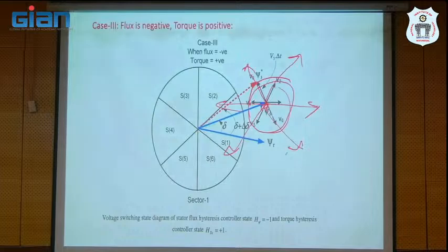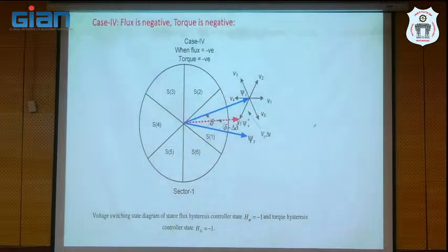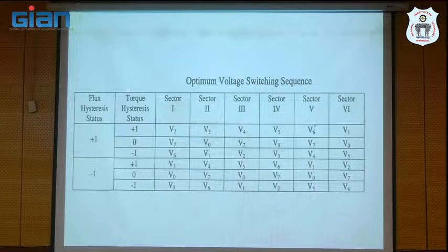If you take care of torque and flux in each sample, then over the period, the resultant response will come in phase with your reference. That is the beauty of the direct control method. Finally, this is about the optimal switching table and switching sequence for direct control. The switching table is called the heart of the controller, right?